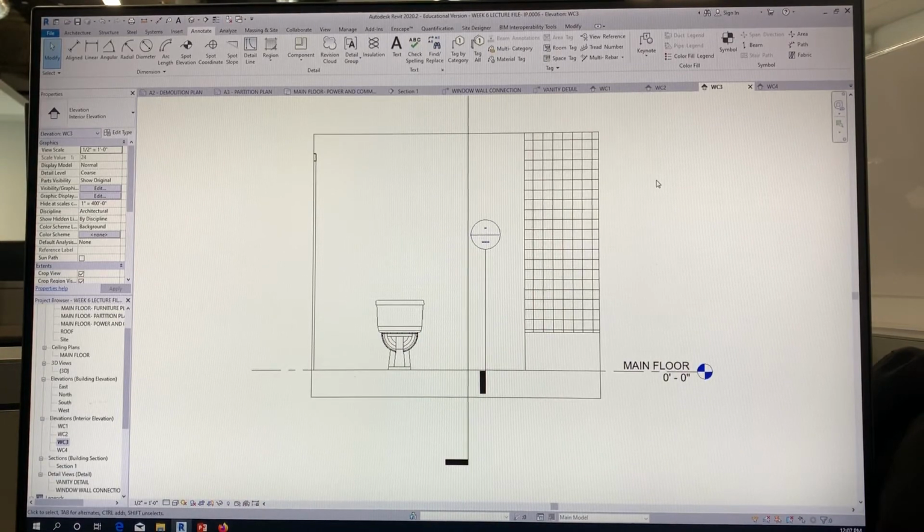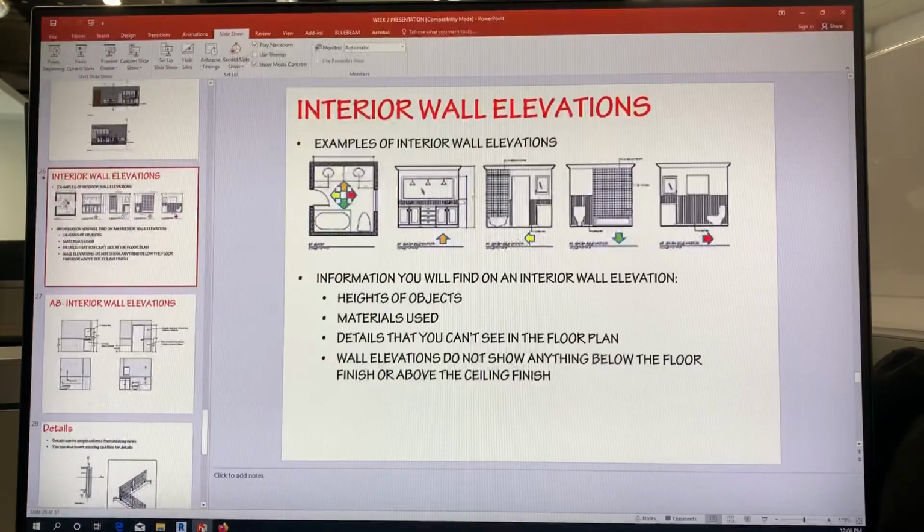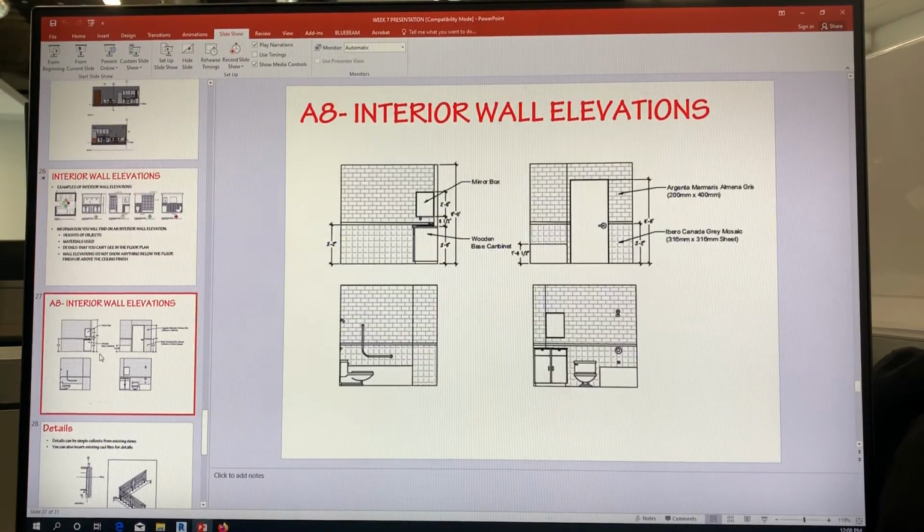Again, hatch patterns are called region fills. And the majority of times, if you're not using the ones that appear in the primary list, edit type, duplicate, and then choose the pattern image. So that's what I expect on yours.